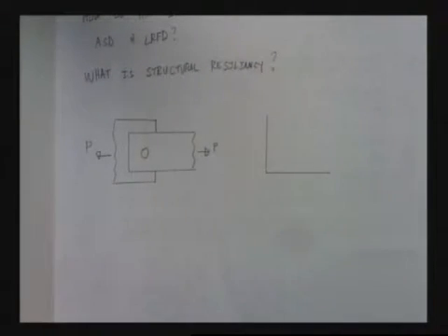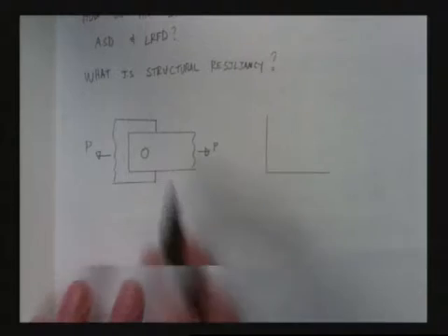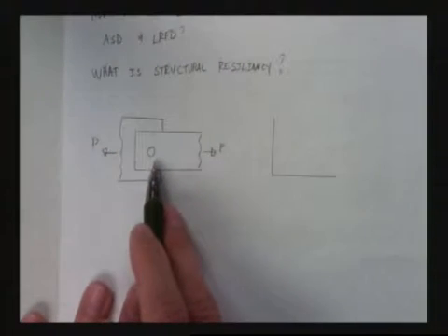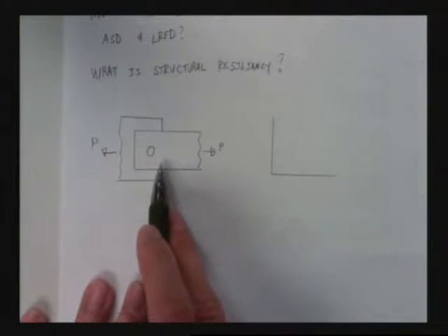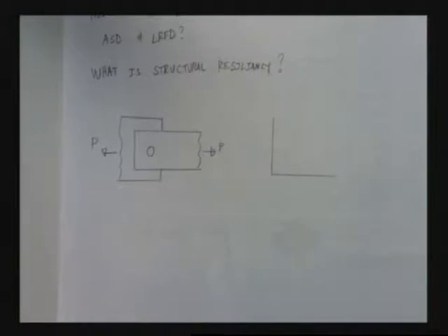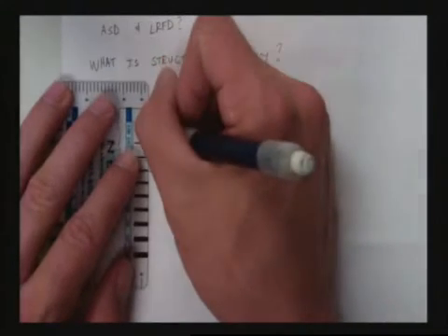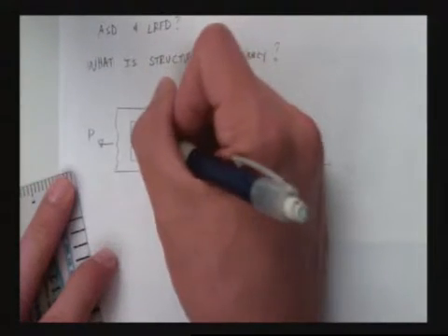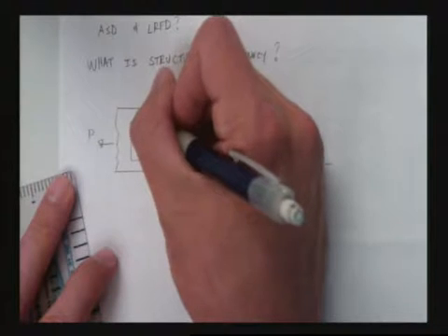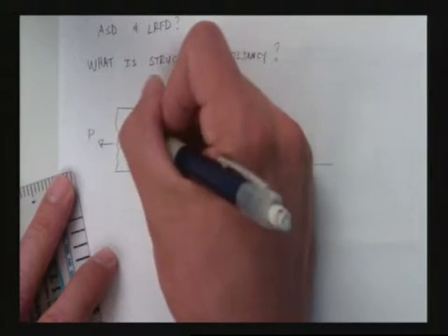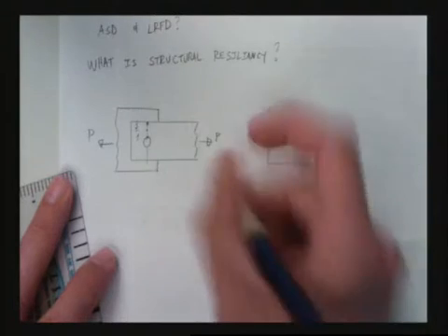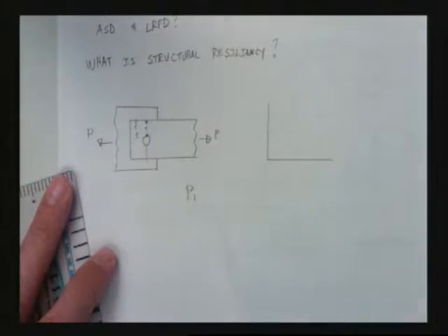Okay, I had a graphical thing that I showed for structural resiliency, and I had two plates being hooked together with a bolt. You could do a weld if you wanted to, but it's easier just to talk about bolts. I had a line drawn on there, and we were thinking about what the stress was at different points: point 1, point 2, and point 3. For P1, for a low amount of load, what's the stress distribution going to look like around the hole? Is it going to be uniform?